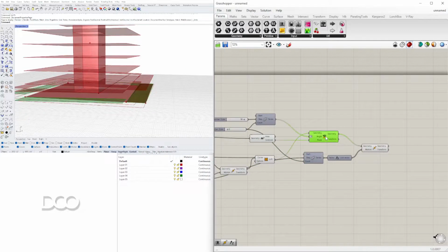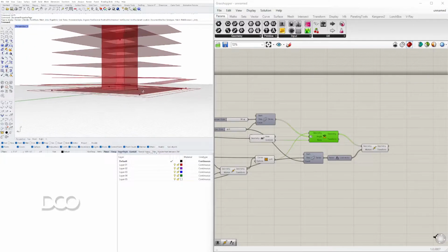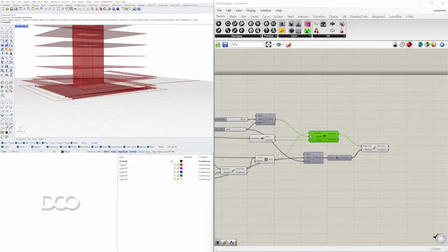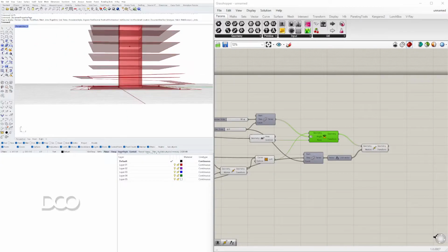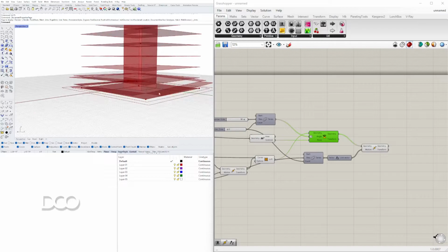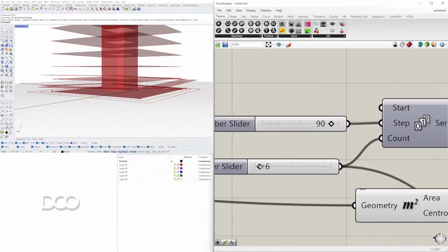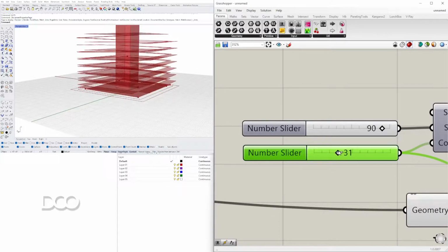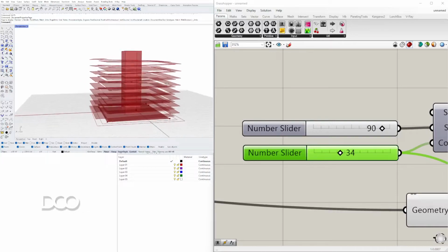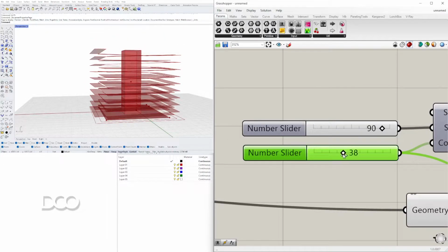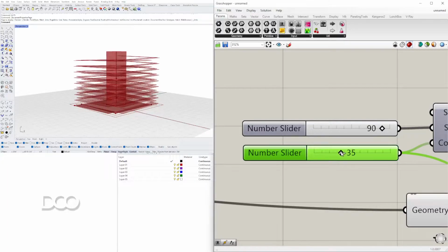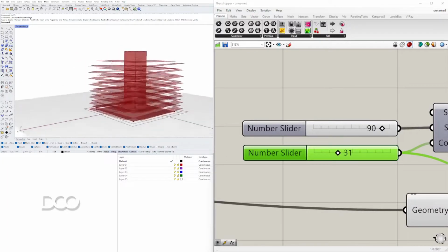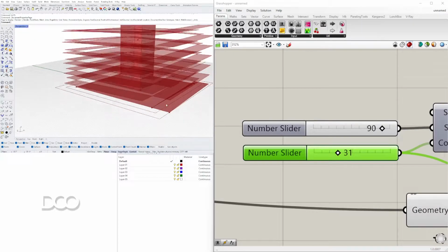So now what I'll do is I'll take this one and I'll disable preview because we're seeing the old ramp. And now when we start here, it ramps up, then it moves up by that amount, then it ramps up again, then it moves up by that amount. So now we can add more ramps to work our way around that design. And it kind of works independent of the building. This way you can either start or stop anywhere before or after, right? So in my opinion, that's a really neat trick.